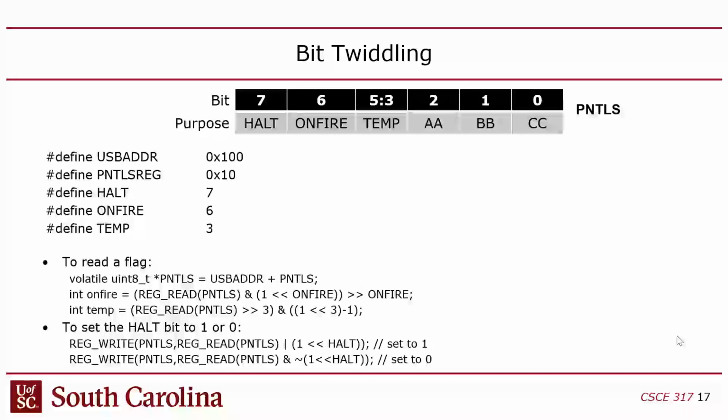Okay, but in order to avoid all this issue, typically you'll have a macro to do this. So notice there's something called reg read, right? If you use reg read with the address, it'll essentially act as a dereference, but it'll ensure that it gets generated properly in the code. You guys probably remember the Nios processor had a similar thing.